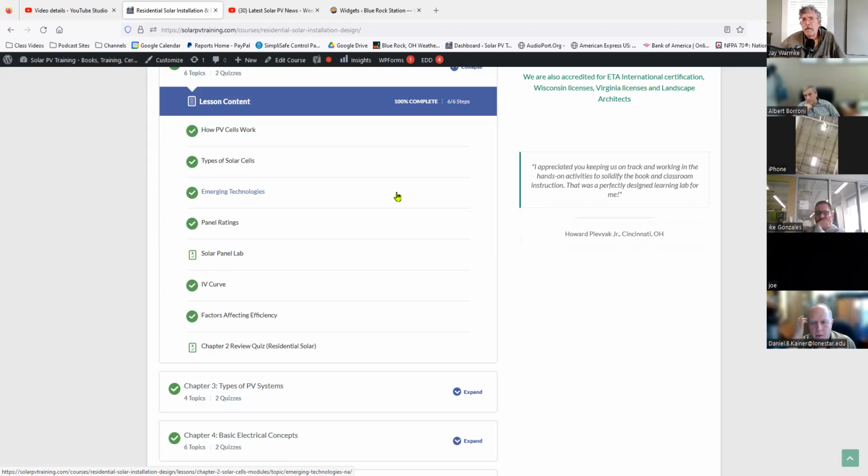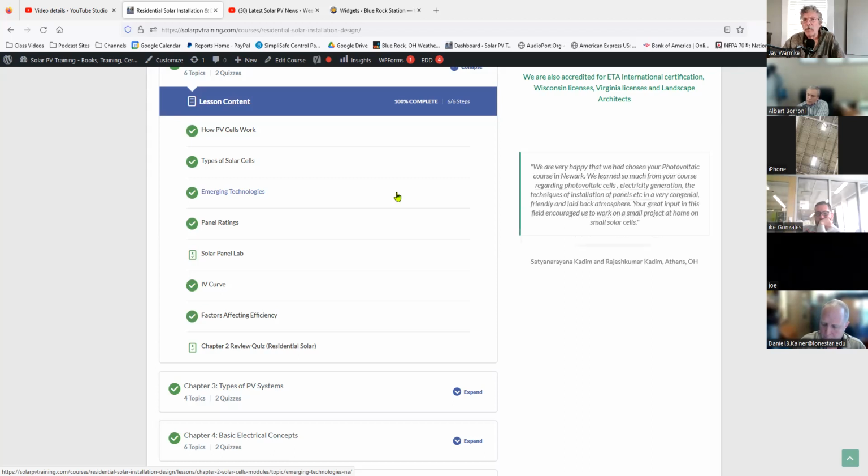They use cadmium telluride, which is a technology that's really been promoted by First Solar, which is the largest manufacturer of solar panels in the United States. And they're arguing that it absorbs over a wider bandwidth, works better in low light situations and higher temperature situations, and has less degrading over time. So they're arguing that initially you'll get 10% or more better production from the thin film panel than silicon, and that only increases over time.